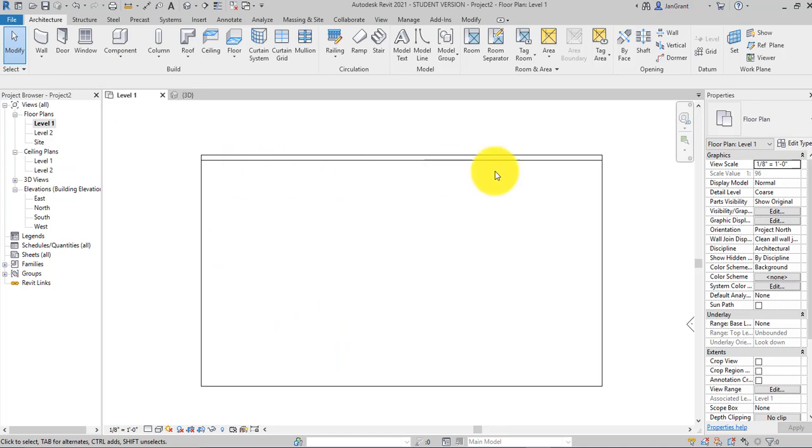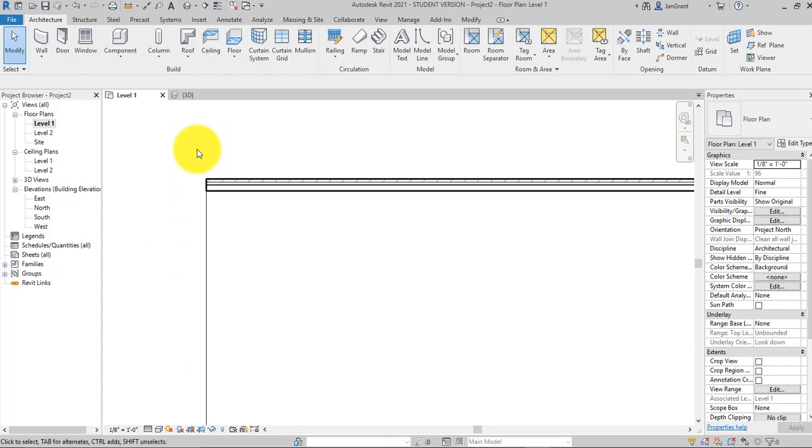Notice that the wall is made up of several components, but you can't see them because at the bottom left corner, we're on the detail level called coarse. The white box there at the bottom left corner, we can change that from coarse to fine. And when we do that, you can zoom up and see that Fine will show you the detail level that represents those different layers in the wall.